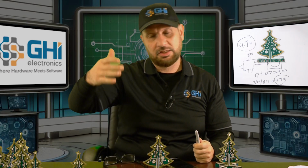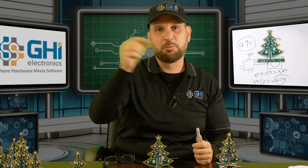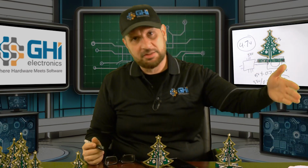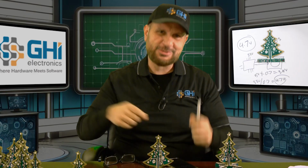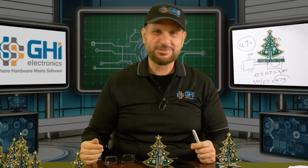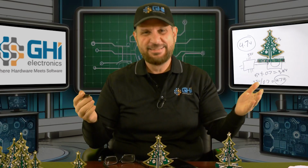And when the LED is powered off 3.3 volts, the concern we had before was not an issue anymore, because the high level needs to be 0.7 times 3.3. We are within range. Everything would work as expected. Added the wire, tested a couple of them. Everything worked great. Then we had to go back and manually, on hundreds of boards, cut the trace and add a little wire. But at least we managed to get these out to our friends and partners. Some received before Christmas, some received after Christmas. But hey, it's a fantastic tree.